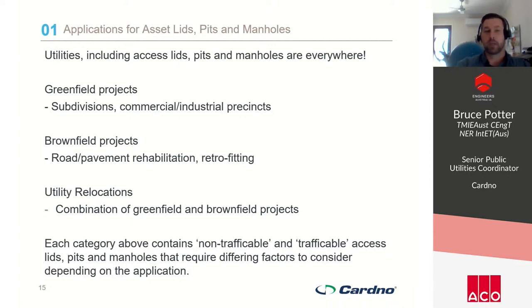When we start a project, they could be in greenfield projects where we're doing subdivisions and industrial and commercial precincts, where essentially there are no existing assets and we're putting those assets in to facilitate the buildings that are going up around it. They could also be in brownfield projects, where you've got road and pavement rehabilitation projects, or you're retrofitting, which could include raising or lowering existing pits and manholes to suit the new surface levels. And then you've got relocations, or where an asset owner comes in and puts another asset in. That's a combination of greenfield and brownfield projects.